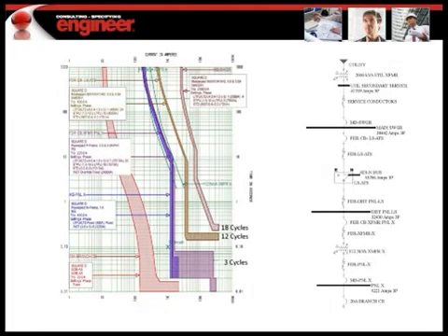And what we wind up with is a transfer switch that has to be able to withstand at least 38,500 amps of fault current, and that it has to be able to interrupt that current for at least 12 cycles. So this is a rating that probably is beyond that which has been tested for a 400 amp switch.